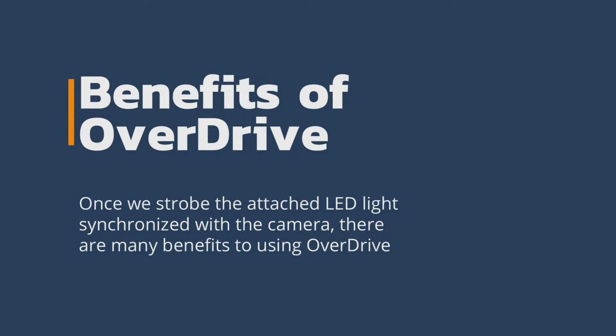So now that we know what overdrive is and that we can get an extreme amount of light from the LED for a very short period, as long as we rest it for some slightly longer period, we want to look at what happens when we synchronize the light in a strobing application with the camera and how we get benefit from overdrive. How are we going to use it? What kind of benefits do we get? Why do people do this? And manufacturers supply these kind of functions.